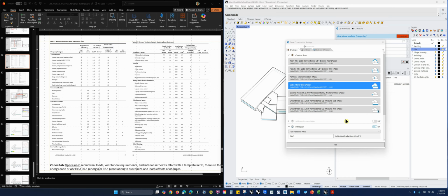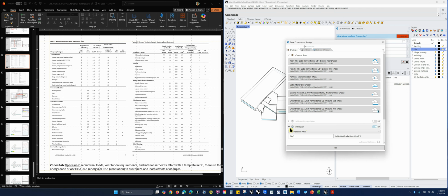We've got our presets. What else do we have in this particular dialog? We have infiltration. This is how airtight the building is. We've talked about this before. We have four control layers, right? One of them is air. We have vapor, air, thermal, and liquid water. This setting is very low. This is for a commercial building using 90.1. I think that the code in New York City is you have to be at least 0.25. That's the energy code.